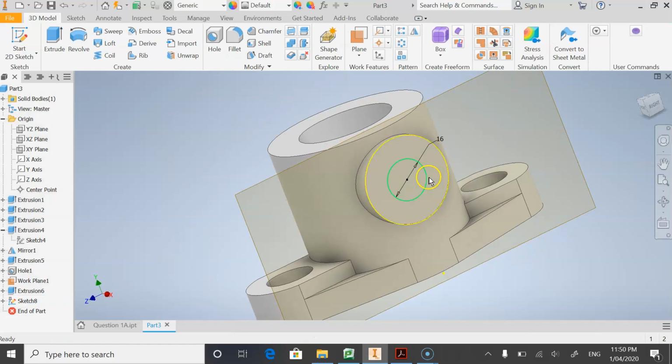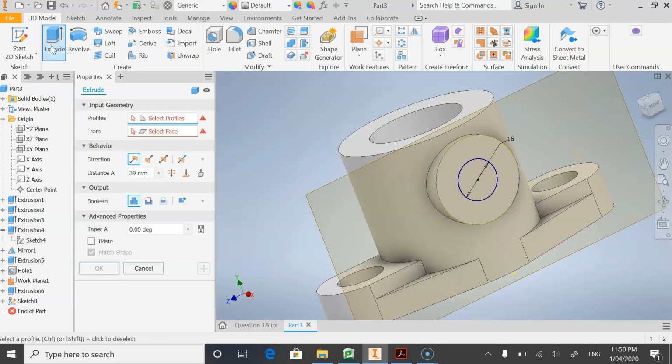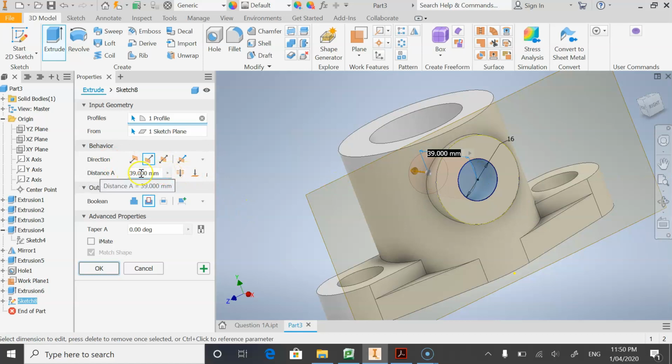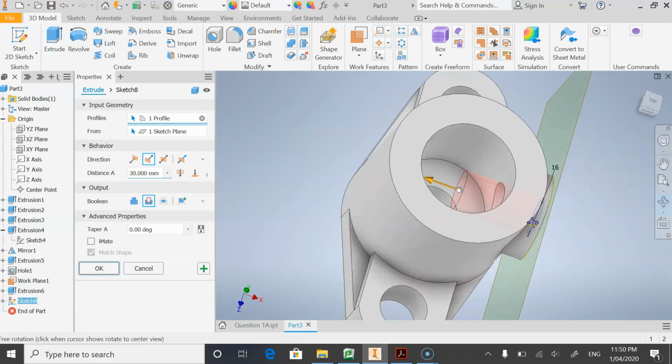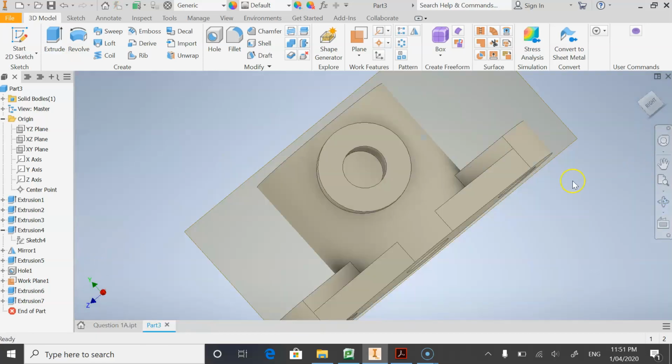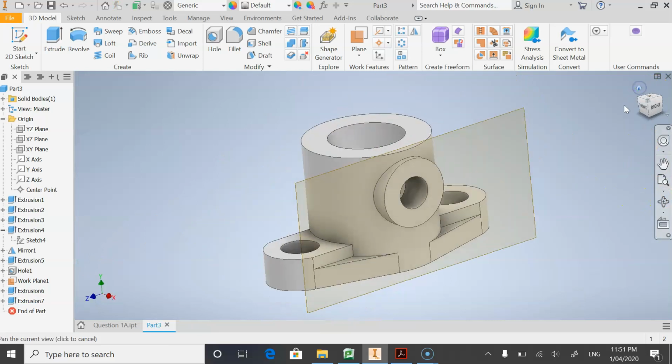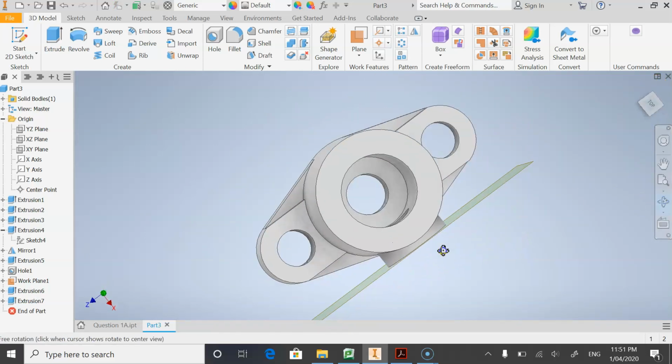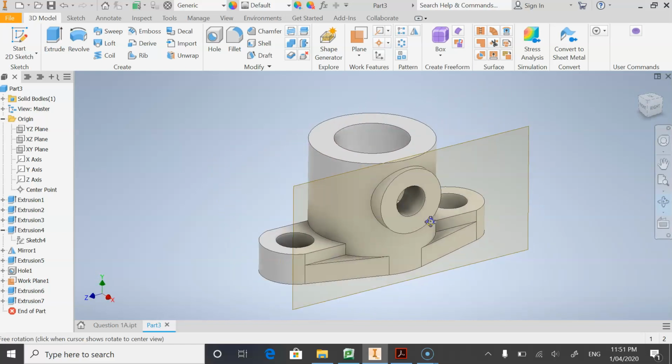Finish sketch, and then extrude, flipped, cut, choose, and then we cannot do all the way through, and we can just assign a number 30 to make sure that is all the way in, and that's it. Okay, so I choose home, and then I finish sketching. I finish the drawing of this shape.